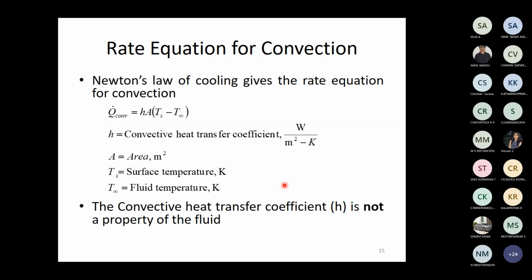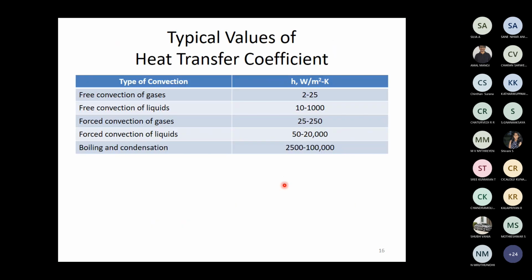Therefore, boiling and condensation processes are suitable when you want to transfer large amounts of heat. Especially, remember, in boiling and condensation, the temperature of the fluid undergoing the process remains constant. Therefore, when you want to transfer large quantities of heat at constant temperature, the ideal processes are boiling and condensation.